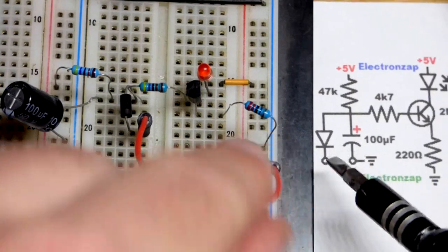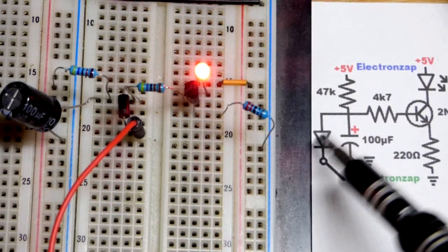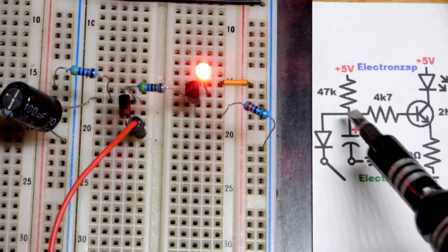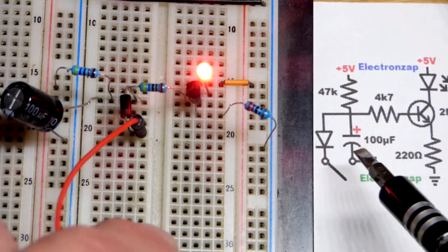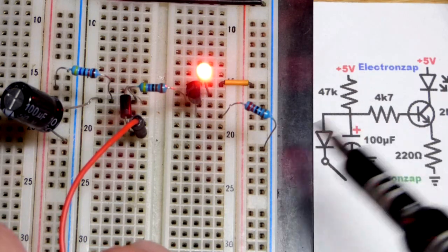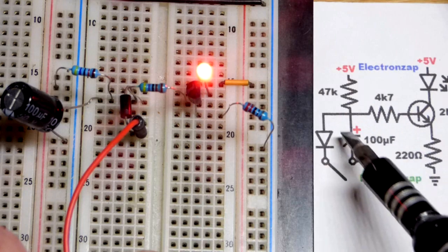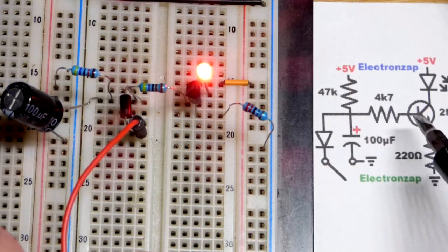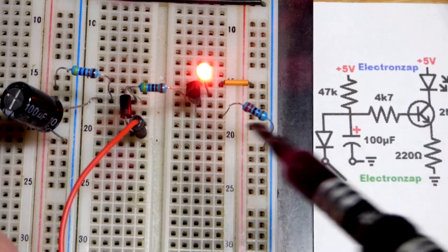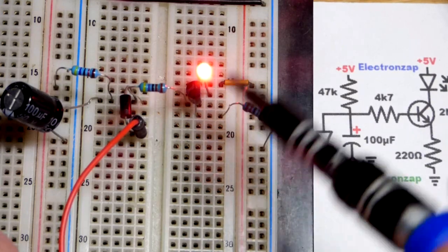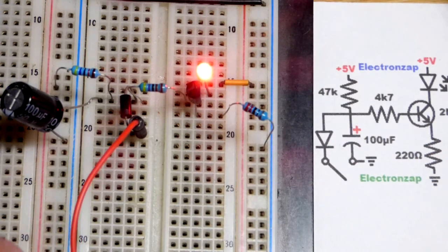Which brings us to the capacitor. When I open the switch, the capacitor can start charging. It was holding 0.6 volts because we were discharging through a diode, which also drops about 0.6 volts. So it was holding up about 0.6 volts. But once the capacitor started charging, you saw the LED get brighter, because as the voltage went up, more current started going through base to emitter. It started seeing a higher voltage. The voltage rose across the current setting resistor, and therefore more current had to go through the LED and transistor.